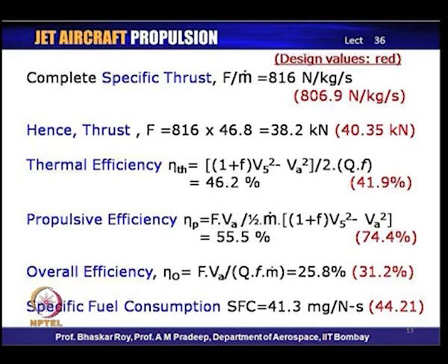the design point value, where we get 44.21, which means that the specific fuel consumption at this operating point is actually slightly less than the specific fuel consumption of the design point, which was a flight Mach number at altitude of 12 kilometers at Mach 2. So, we have calculated the engine parameters at an off design operating point, which is defined at altitude of 9 kilometers and at Mach 1.5, and compared all the parameters with the design point parameters.